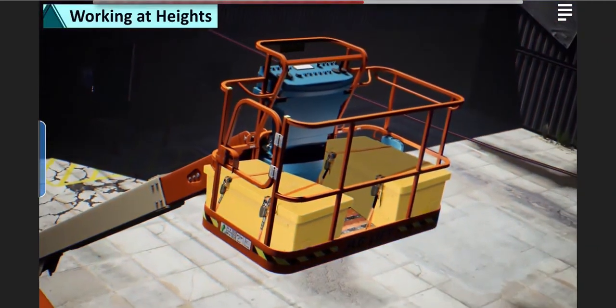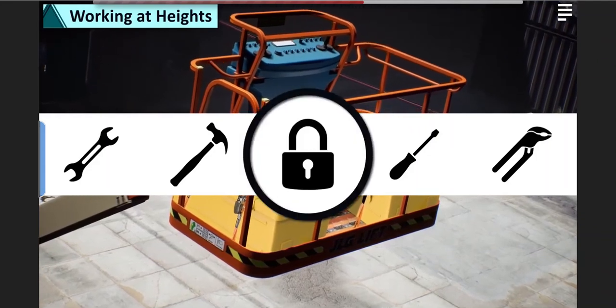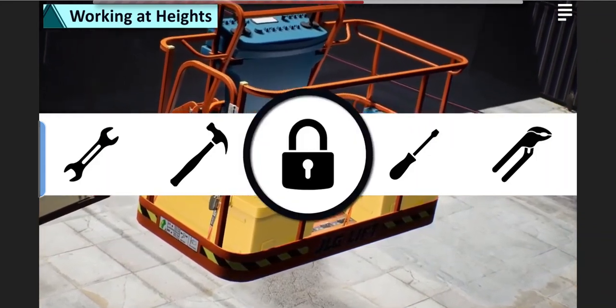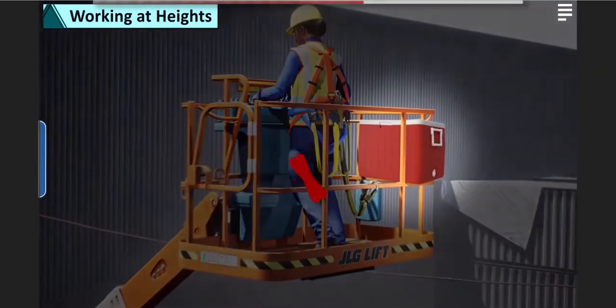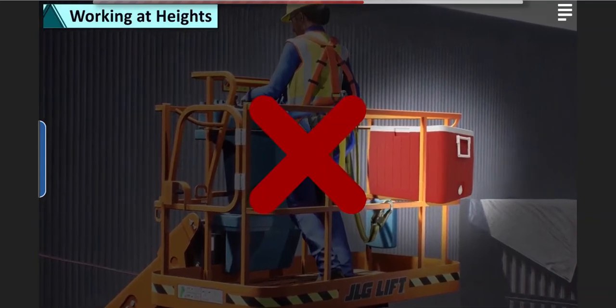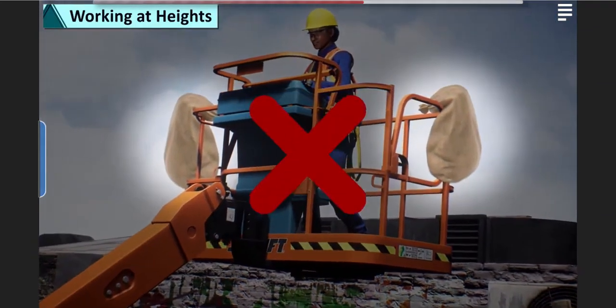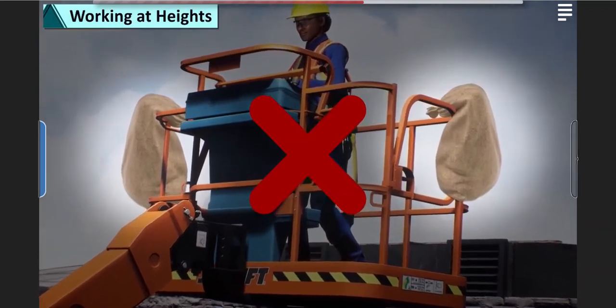Tools and materials on the work platform must be properly distributed and secured before driving the MEWP or positioning the platform, and should remain secured when not in use. Never carry materials larger than the platform or supported on the guardrails, unless this use is approved by the manufacturer. Never carry materials outside of the work platform, except in a manufacturer-approved carrier designed for that purpose.